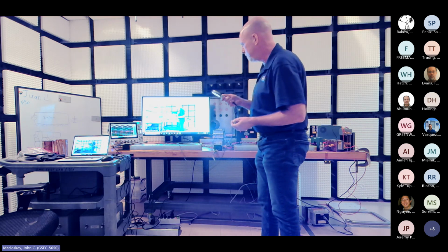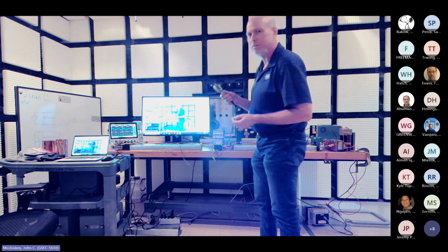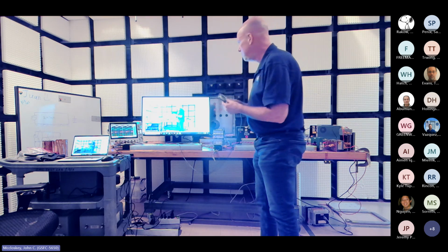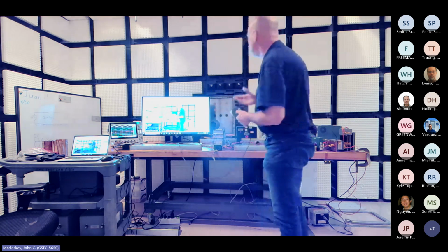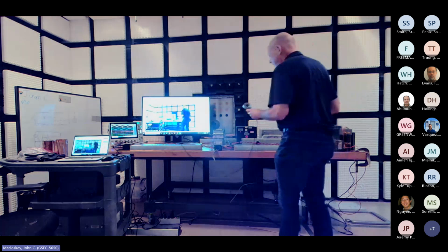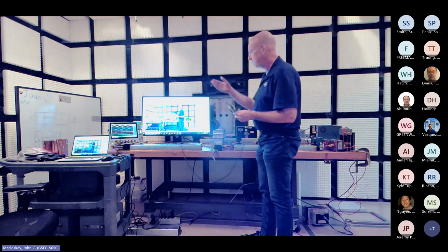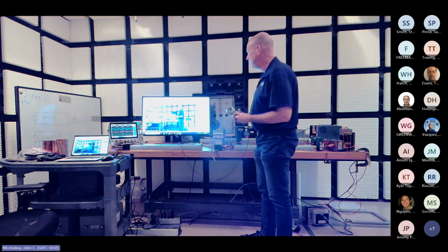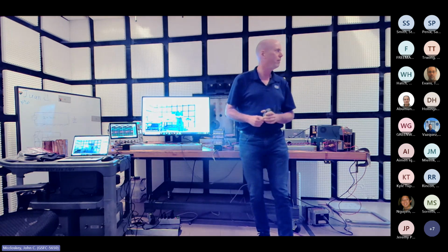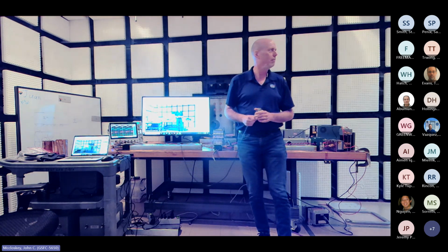Even in the frequency domain, these measurements take a few seconds. I guess if you have one of the older EMI receivers, it might take a couple minutes, but if you have an FFT receiver, it takes a few seconds. And if you're looking at it in the time domain, it's very quick. So a traditional receiver is about a 5-minute scan, where the FFT is seconds.